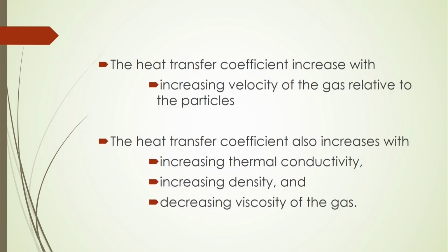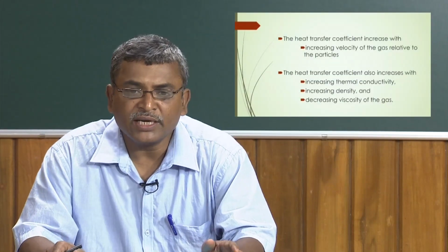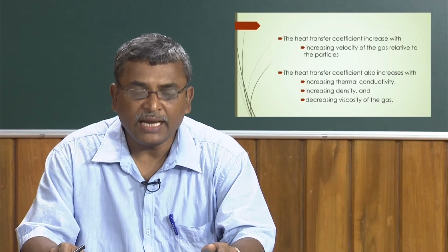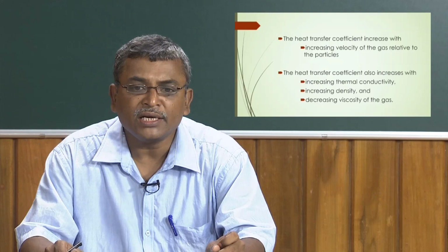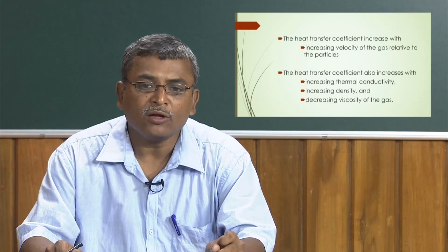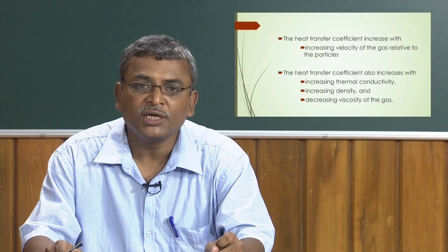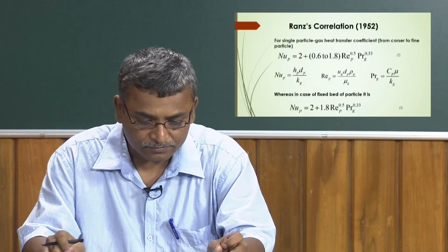Also, this heat transfer coefficient will increase with increasing thermal conductivity, that means the physical properties of the system, the physical properties of the particle, even particle density, even viscosity of the gas. It will increase with thermal conductivity and with density, and it is very interesting that the heat transfer coefficient will decrease with the viscosity of the fluid.